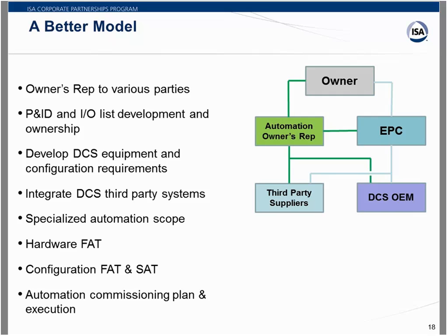One of the larger tasks that makes a lot of sense for them to do is to really develop the DCS and automation equipment and configuration requirements, and that's a big job, right? The functional specifications, cause and effect diagrams, recipe descriptions, whatever it takes to define what the configuration requirements are, not only for the DCS, but for these other programmable devices that may exist out in the field that also need configuration. So that's a pretty big task.